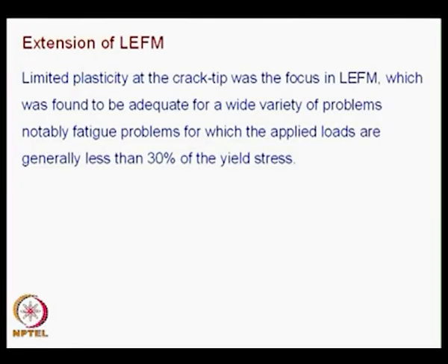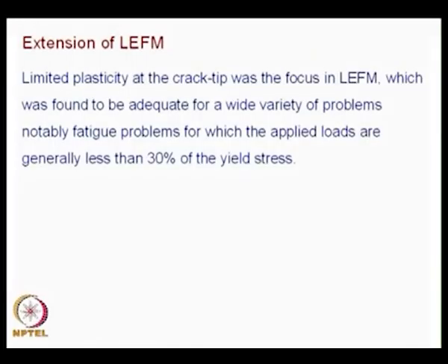and with that you could solve a variety of problems. So, that is an advantage. You had certain pressing need to understand how cracked structure would behave. You could immediately apply it to a variety of problems, and another point that you have to note is, notably for fatigue problems, the applied loads are generally less than 30% of the yield stress.